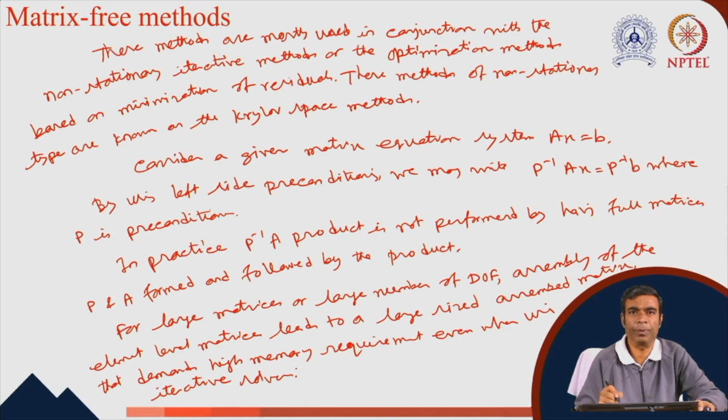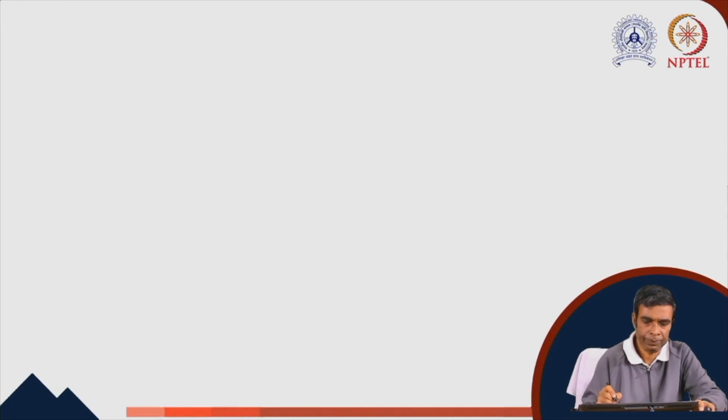Therefore, the concept of matrix-free method is that we do not perform the assembly. We write the element level contributions and perform our operations at the element level contribution itself.